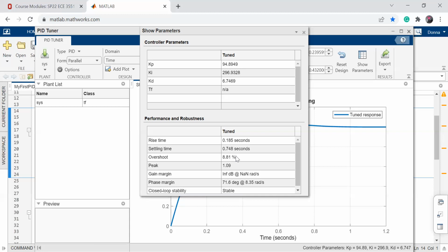So all of this is on paper, right? Once you get these numbers, you have to apply them to your system: the digital controller type and microcontroller, whatever your computer is. Run it, measure things, and then measure the time of 10% to 90% of the performance.